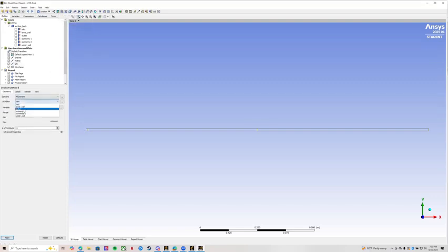We're going to go ahead. Location is going to be symmetry, so you can pick that whole body. Switch it to velocity U, which is what we want to measure. And we're going to do 110 number of contours. Once you press apply, let it load for a little bit, and then we'll give you that contour profile.